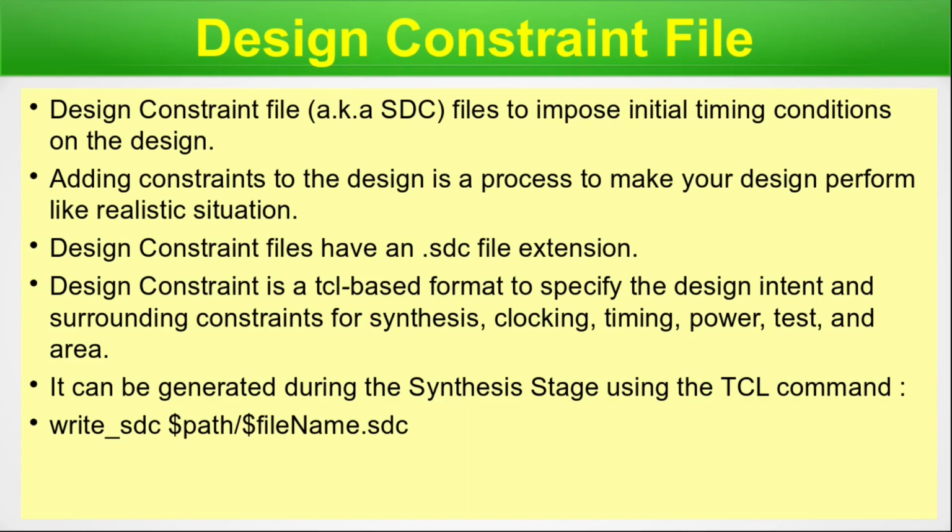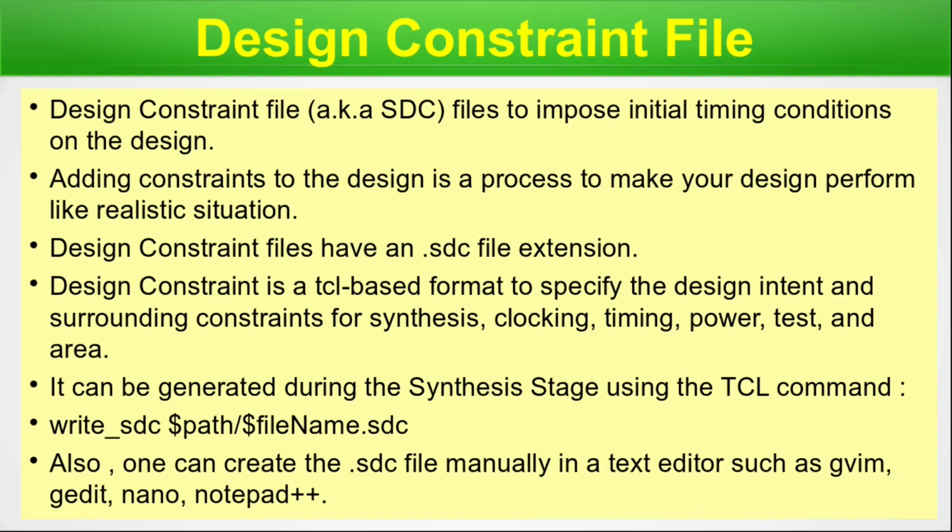So don't think I'm making a global comment, but generally tools have this capability to read the SDC and write the SDC at the synthesis stage, and it may vary from one vendor to another. But just for your knowledge, apart from writing it by hand, you can dump it also. Also, one can create the .sdc file manually in a text editor such as gvim, gedit, nano, Notepad++. I don't know which text editor you prefer. You can write in the comments below which text editor you are most comfortable with.